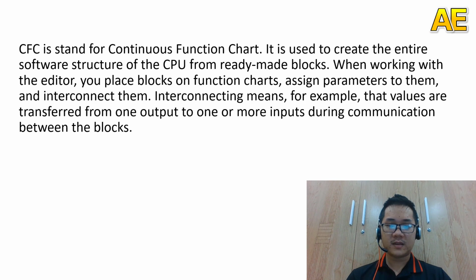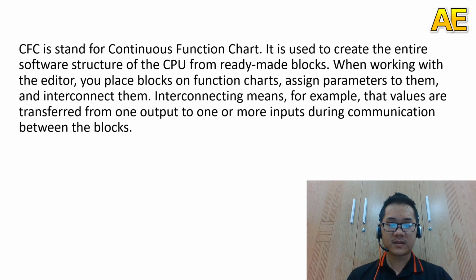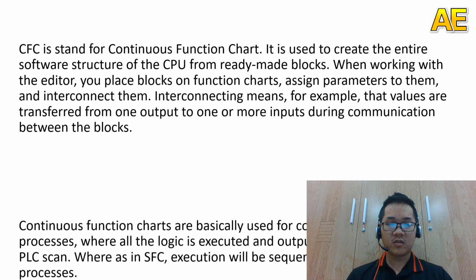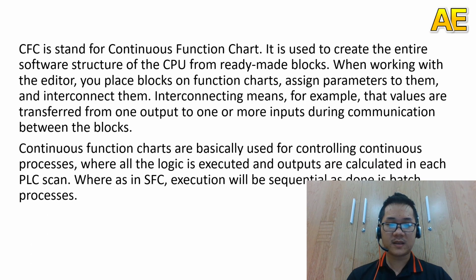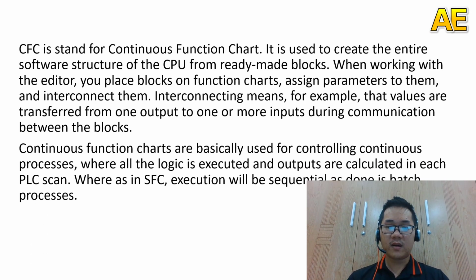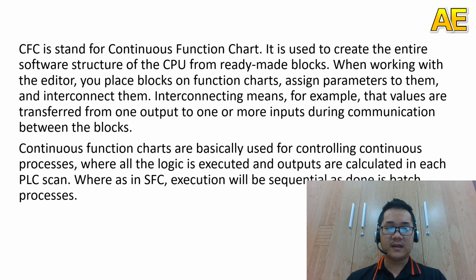Interconnecting means, for example, that values are transferred from one output to one or more inputs during the communication between the blocks. CFC is basically used for controlling continuous processes, where the logic is executed and outputs are calculated in each PLC scan.